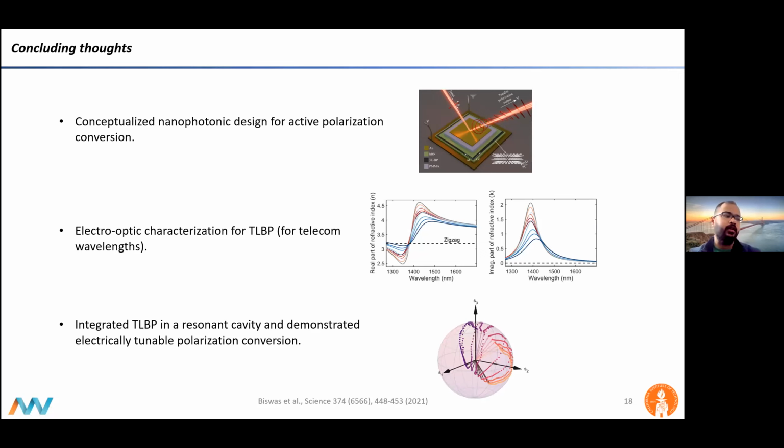Yeah, so that's actually a challenge we faced in a lot of our fabrication. All of this fabrication had to be done in a glove box. But what we found is that when we encapsulate these layers all within the glove box with hexagonal boron nitride, we measured all of these devices over a period of 1 year or 8 months, and we saw no degradation in performance with multiple rounds of measurements and voltage tuning. So once we encapsulate them, they're quite stable.